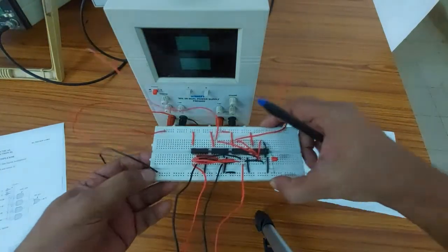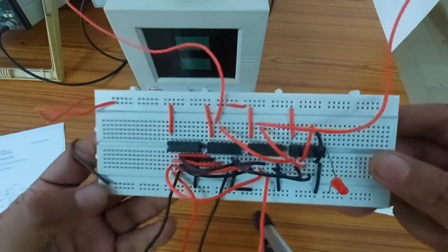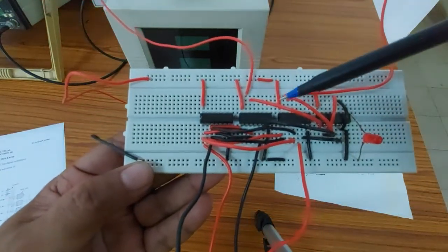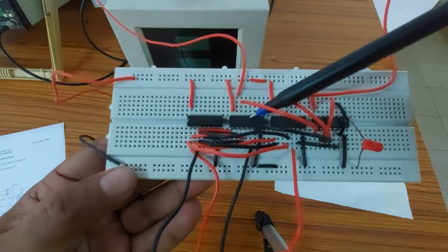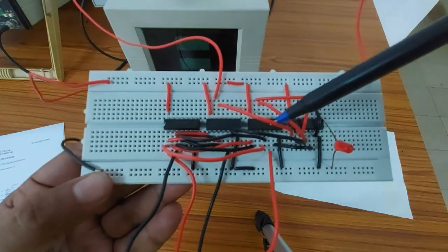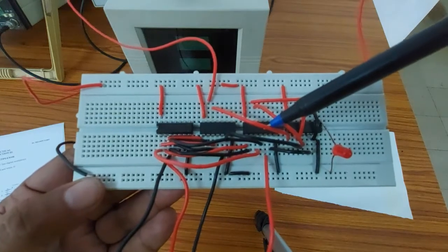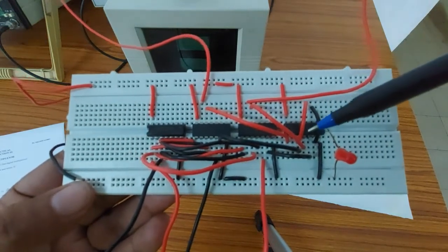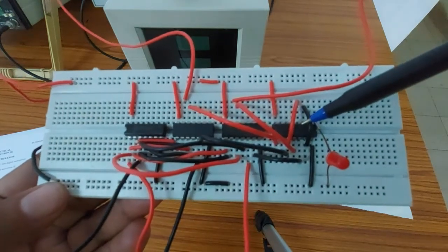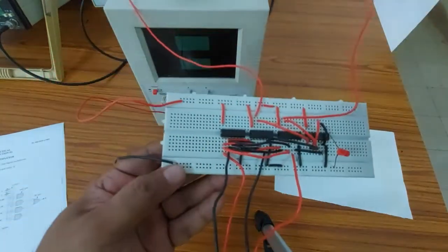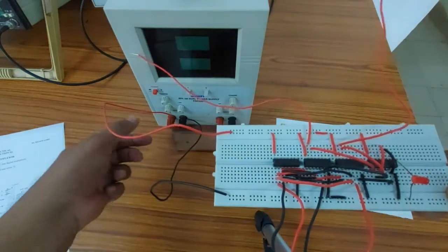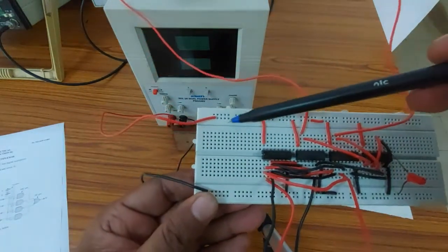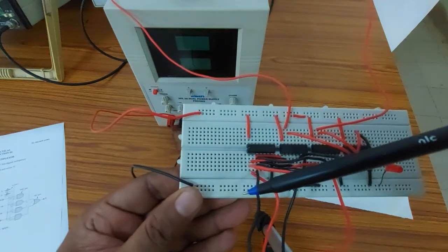So this is the connection which I have made. The first IC is a NOT gate. Then we have 7411, which is the next IC. The third one is also 7411. So I've used 3 input AND gates, NOT gates, and I have the OR gate here. So I already made the connections. I've given VCC in the top line, which is here, and ground, which I've given here down.